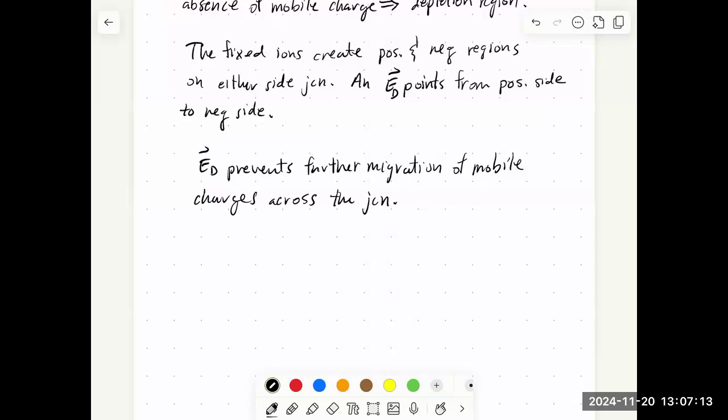Okay, so fair enough. What we're going to try to do is write down what we think the electron current would look like in this isolated diode. So we're going to consider the electron current in our isolated diode. By isolated, I mean we don't have anything connected to our diode. After we consider this case, we'll connect a battery across the diode and see what changes.